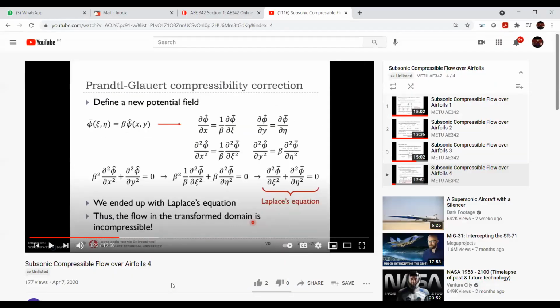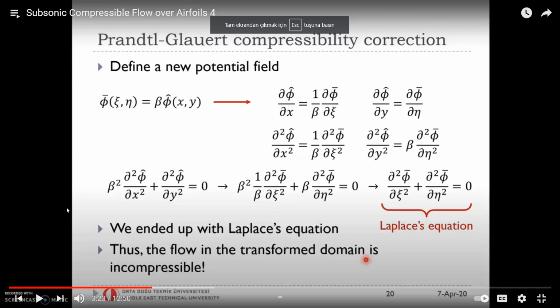It's actually quite a simple equation. You don't need to solve any equation for compressible flow. You just obtain, for example, a panel method solution, and if it's up to Mach 0.7, you just multiply it with a correction factor. You get the Cp value for the compressible flow. Anyway, we will see now in a second. Let's continue.